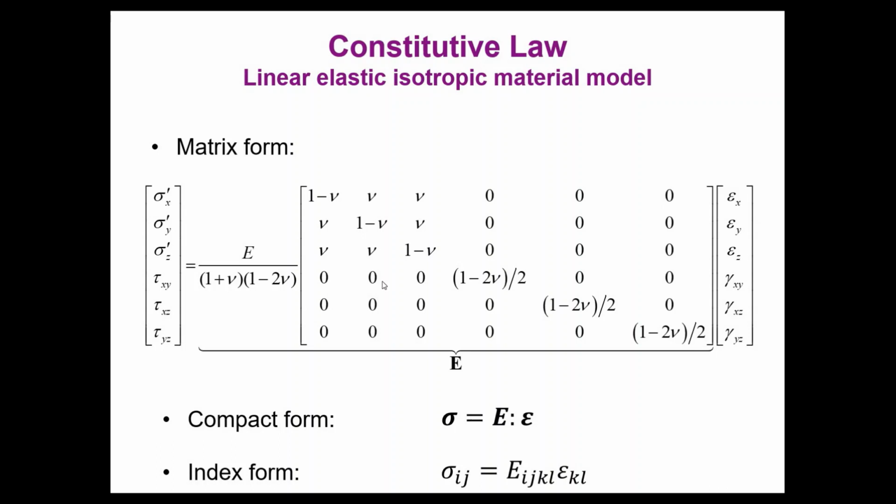So in this case, with just these 2 parameters, the Young modulus and the Poisson ratio, we have defined the relationship between the stresses and strains of these materials defined mathematically. But when we have plasticity, this is not enough, as we are going to see in a moment.